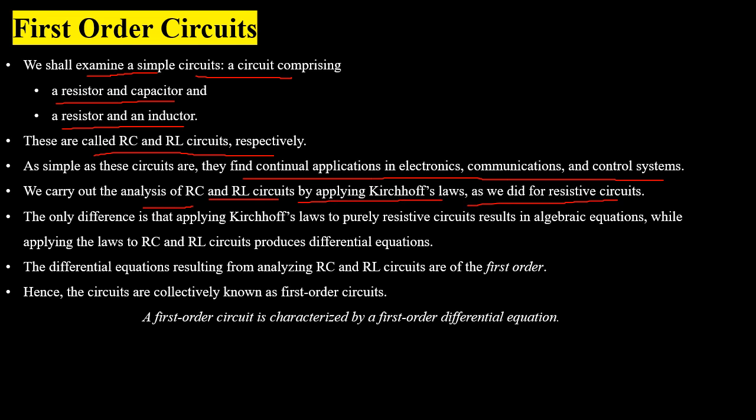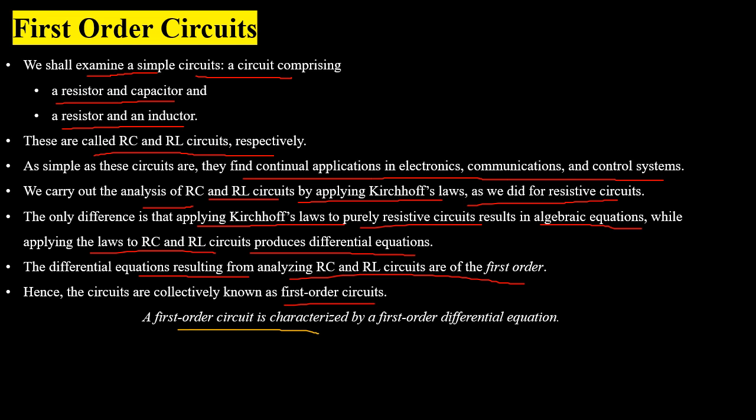As a result of applying Kirchhoff's laws on resistive circuit, you obtain algebraic equations, whereas if you apply Kirchhoff's laws to RC or RL circuit, you will get a differential equation. And these differential equations are of first order, and hence these RC and RL circuits are collectively known as first order circuits. And by definition, a first order circuit is characterized by a first order differential equation.